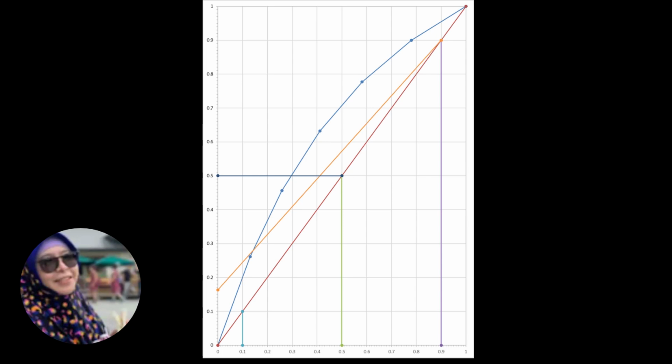For this question also, you are given that the feed is at saturated vapor. So when it is at saturated vapor, the value of q is equal to 0, which is a definite number. Therefore, when q equals 0, the q operating line is only a horizontal line.